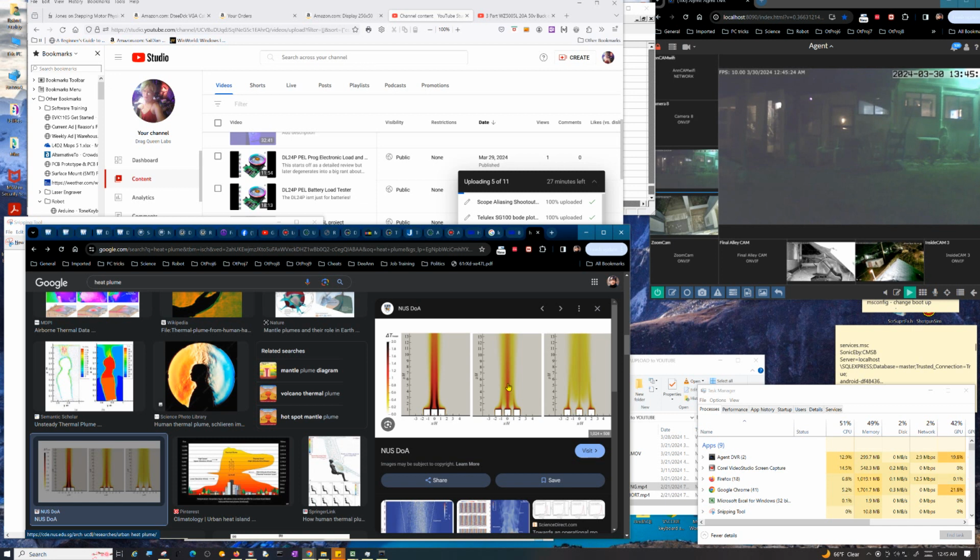So if you're designing something that's going to go on the side of a building, well then you've got to take into account how much heat is going to be coming from the ground and the side of the buildings. It can get awfully hot. You'll get heat plumes off that too that are maybe going to go right into your enclosure. So that's going to really affect it. But the point is, you still want to take a measurement in your enclosure in its expected environment.